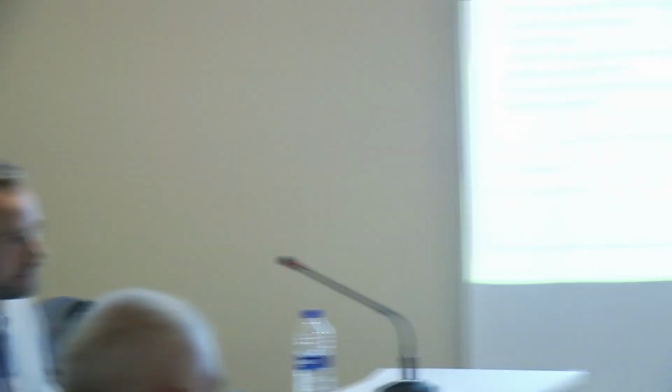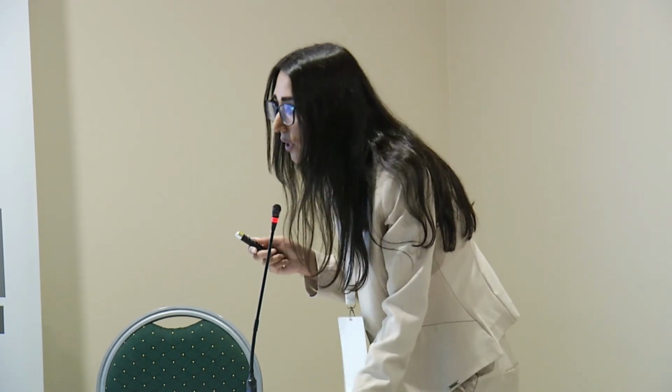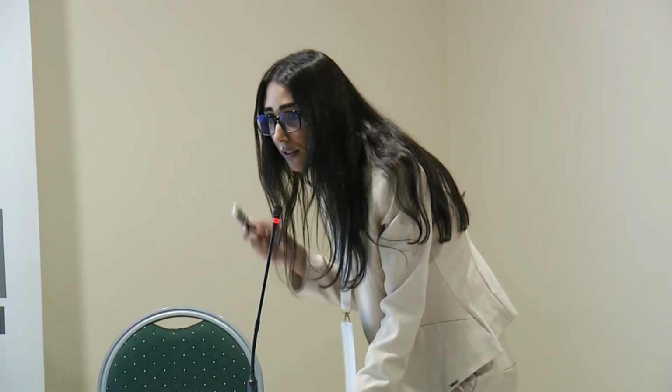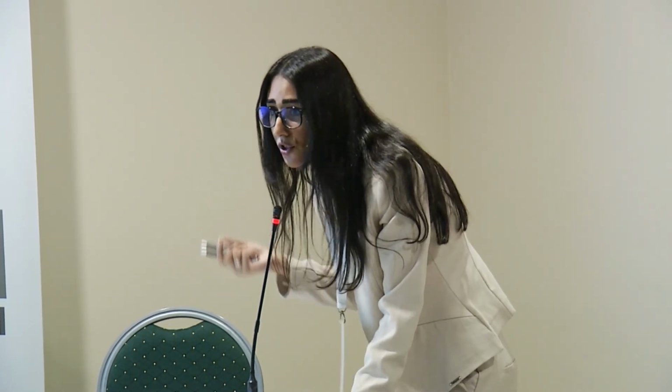We developed the expression of the current in each elementary section, since the tape is discretized into different rectangular elementary sections, and we calculate the current in each little section, so we can have the distribution of the current inside the tape, which is non-uniform. Thank you.